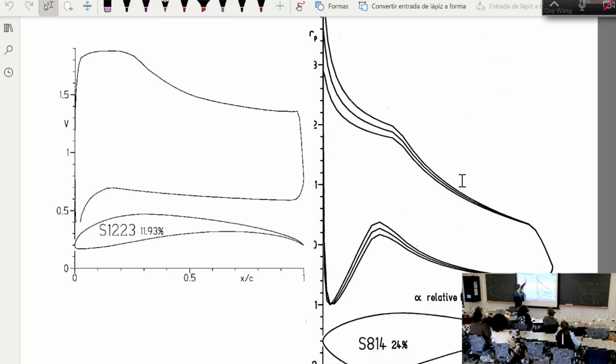Okay. So that's why when the boundary layer is still very thin over here, it is able to withstand a larger pressure gradient without separating. But as you go towards the trailing edge, the boundary layer thickens, and you need to put it at a lower and lower pressure gradient so that the flow won't separate. Okay, so that's for this one.